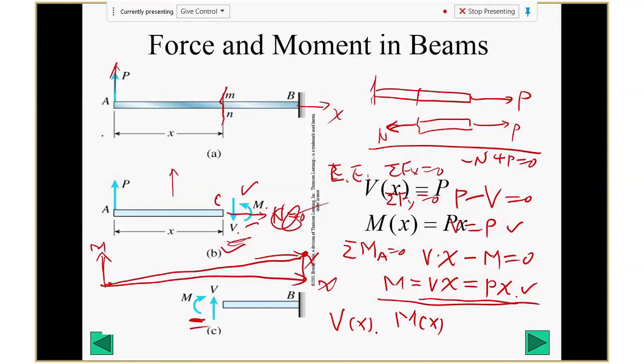Because when you write the equation of equilibrium, you give a direction that's positive. Everything against it is negative. I would elaborate and just remind everyone to be careful. You're not talking about the moment, you're talking about the deformation. It's different. In this class, we always define positive and negative based on deformation.